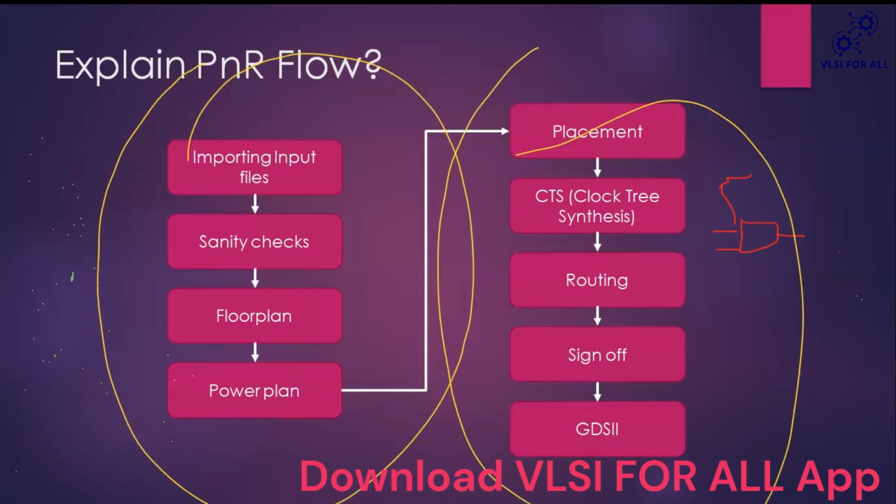The middle flip flop will get the clock early, and later the flip flop in the top right will get the clock. During CTS the tool will try to avoid these things. Instead, the tool tries to do routing to reach the clock at the same time to both flops. That can be done in CTS.